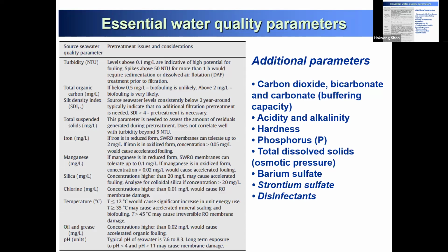It's very difficult to calculate the calcium carbonate saturation point that creates membrane fouling, or what the manganese oxide, calcium phosphate, calcium sulfate, calcium carbonate concentrations and conditions will create.